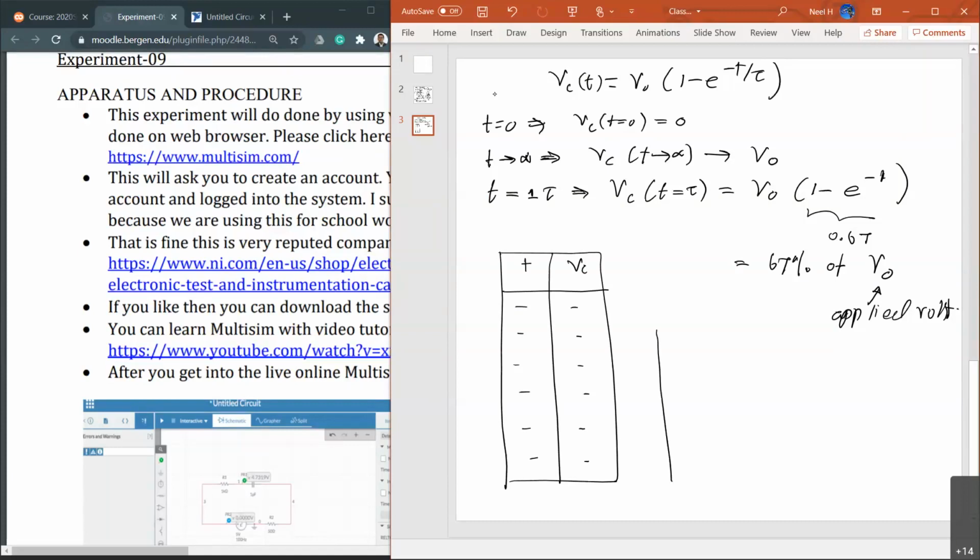We did 2 different types of plot. One plot is Vc versus time. Then you saw it increase rapidly and then approach some sort of horizontal flat line. That is the maximum possible voltage it is approaching, that is V0. Since the analysis using Excel can't easily fit this kind of curve, what we did was change the shape of the graph into a linear one by taking the ln.